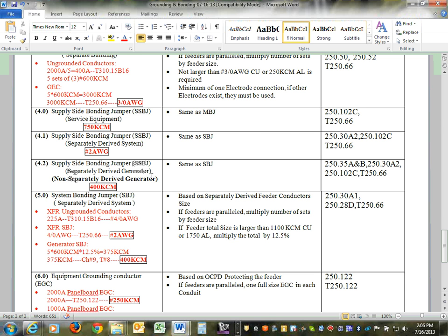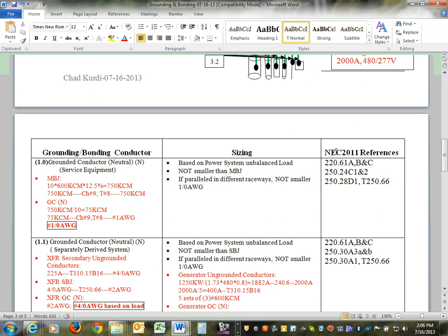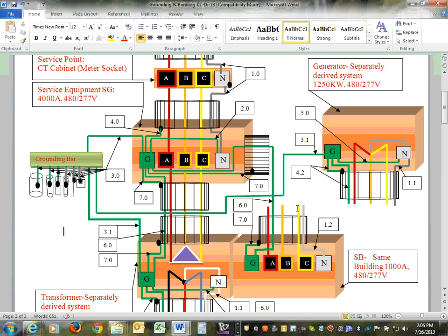Either way, that wire right in here that you bring through your PVC conduit, say you are bringing a PVC conduit, you bring a wire through it, that wire goes all the way to the circuit breaker. So your circuit breaker in this case will be located right in here, that's the confusing part. That wire comes all the way to the enclosure of your circuit breaker. That's called the supply side bonding jumper.